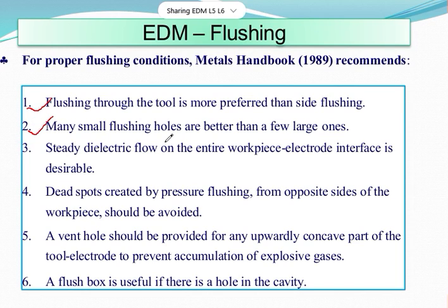Third, a steady dielectric flow on the entire workpiece-electrode interface is desirable. So a steady dielectric flow must be there within the entire workpiece and electrode interface. And the spot that is created by pressure flushing from the opposite side of the workpiece should also be avoided.